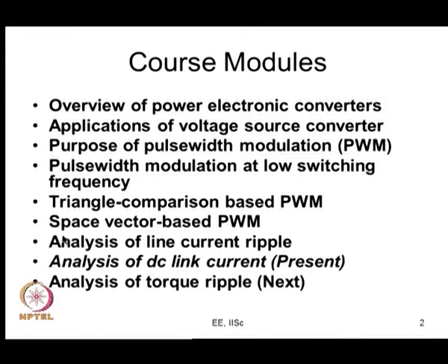That is one burden of the entire course: we have been trying to say that space vector PWM is more general than triangle comparison PWM. Whatever you can do with triangle comparison PWM, you can do with space vector, but certain things that you do with space vector cannot be done with triangle comparison PWM. So in these 3 modules we focused on how you generate the PWM signals. One is at low frequency and the other two are at higher frequencies, one by triangle comparison and the other by the so called space vector approach.